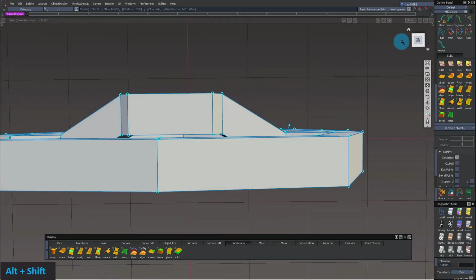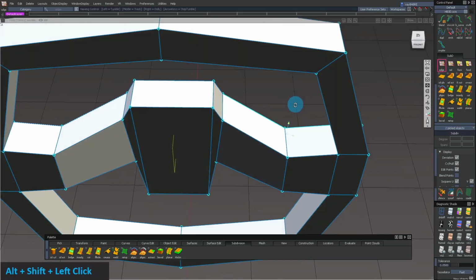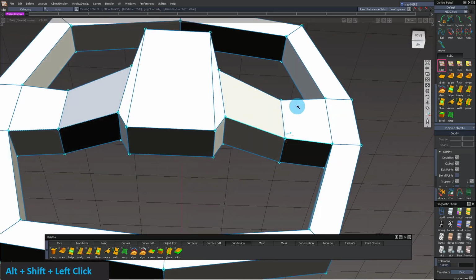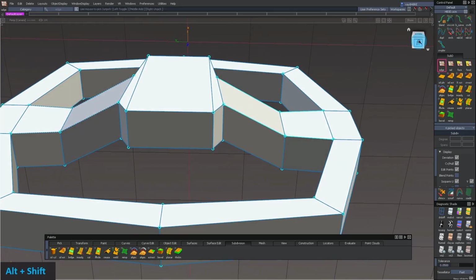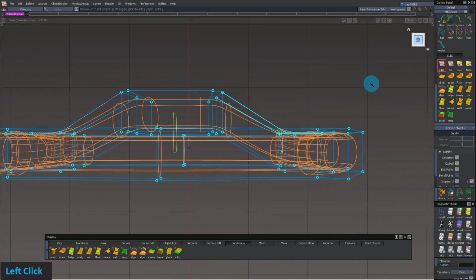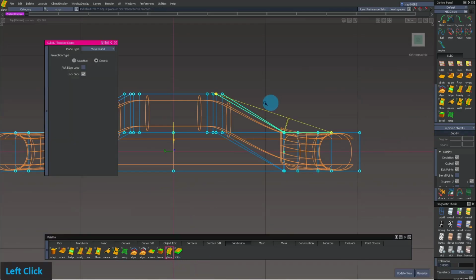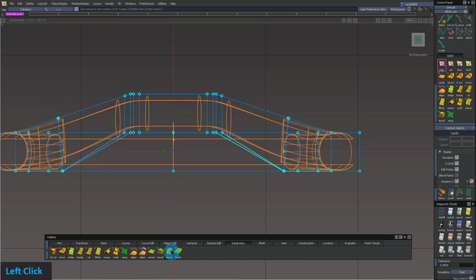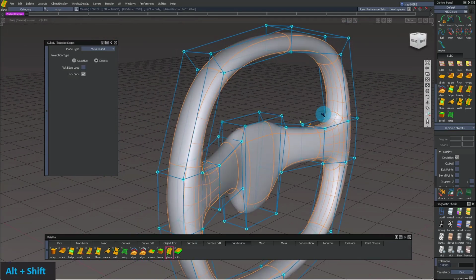So here's a good place to showcase what the planarize tool does. Let's say these two edges, I want to make them straight, and you could use multiple edges to make them into straight lines. How this tool works is you go to whatever angle you want it to be straight, then you hit the planarize tool, which is down here, and that makes them straight in that view. This is very powerful when we're doing a lot of refinement of the CVs.